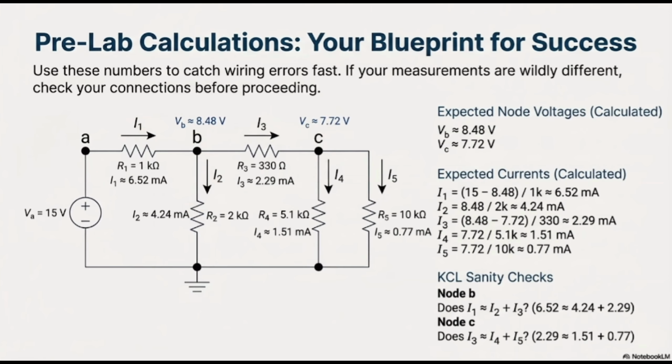For instance, at this point, if I assume that everything is okay, I1 equals I2 plus I3, and at this point I can write down I3 equals I4 plus I5. Or maybe some of you would say that, based on your teaching and your method, you always consider the currents like that. Again, that's no problem. As long as you are considering everything consistently, you still can get the right answer.